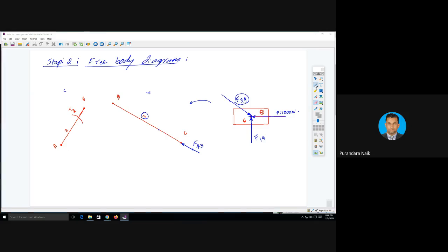See, I told you in the previous case, this is parallel to link number 3, right? If this is parallel, automatically this is also parallel to this one, equal and opposite, okay? This force is equal to this force, and this force is opposite to this force. That's all. Because every element is in static equilibrium. Okay. Finished?